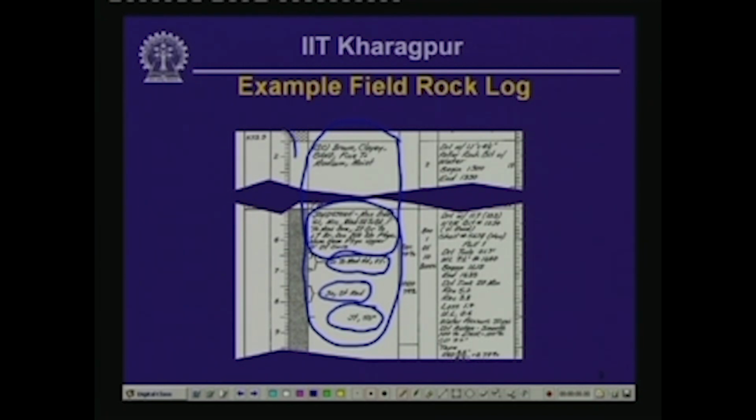And as earlier, further left you have got a depth scale which tells us the thickness of a soil or bedrock layer, or at what depth they are going to be encountered. And then, like earlier, we have got a column which tells us the depths from which core samples were obtained, and how much recovery or how much RQD there is for these core samples or these hand specimens.